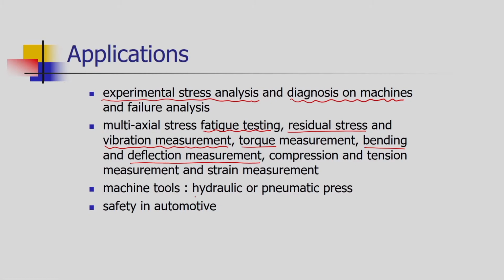In machine tools, particularly in hydraulic and pneumatic presses, since we are applying more pressure, more hydraulic pressure or more pneumatic pressure on the pipes or the elements of these systems, there may be strain, there may be deformation in these mechanical elements. To monitor the deformation of these elements, it is very essential to paste certain strain gauges and get the output from them.